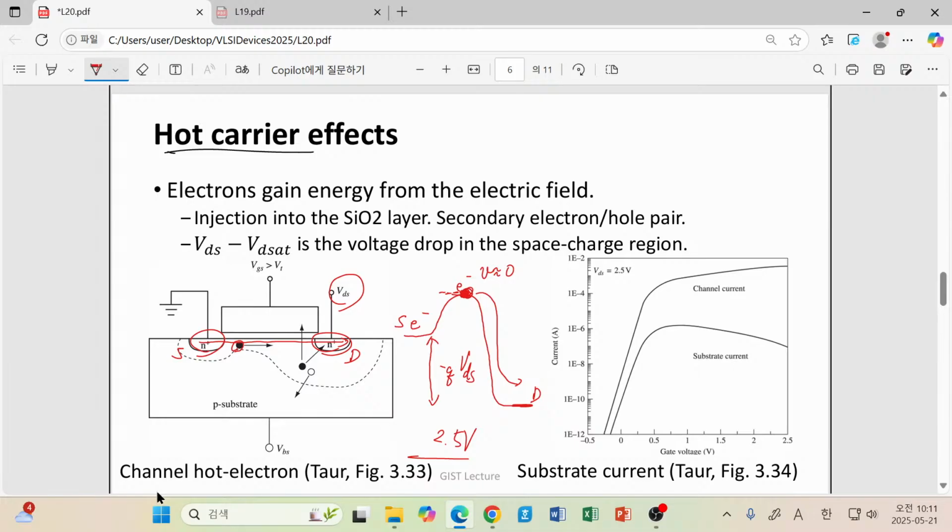So when we have an electron, if we keep its energy level and just move it to a different position, its trajectory will show this way. It means that if we have such a lucky electron, how can we interpret its energetic state? This electron, position-wise, is already in the drain region, and its energy is so high. Why is it so high? Because it does not lose its energy, and this energy is used as the kinetic energy of this electron. Simply speaking, this electron becomes extremely fast.